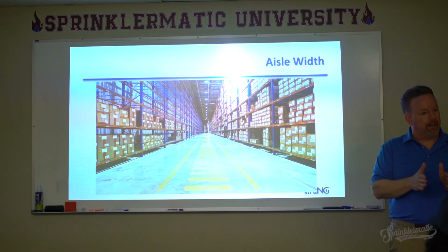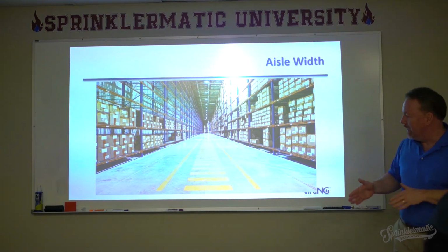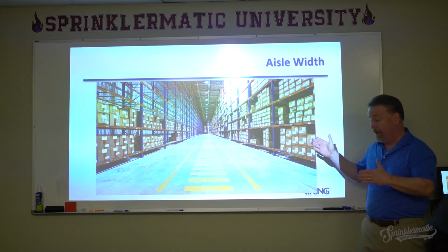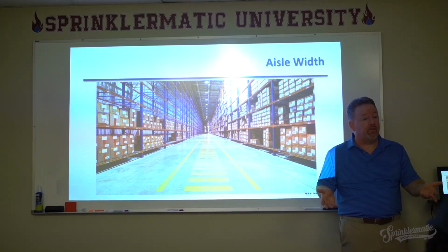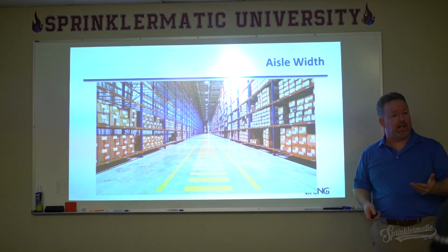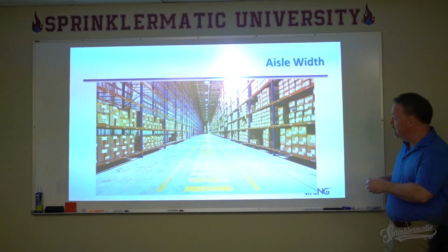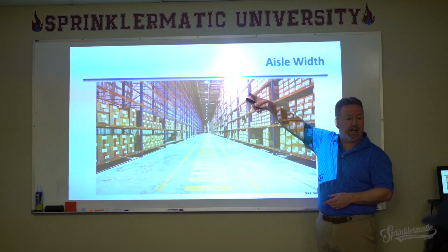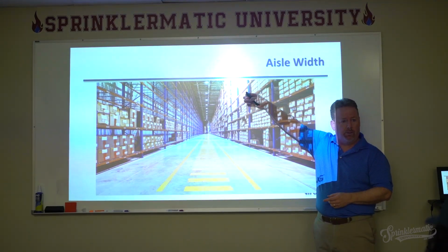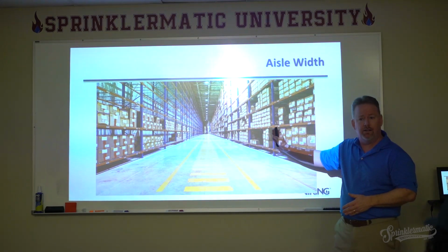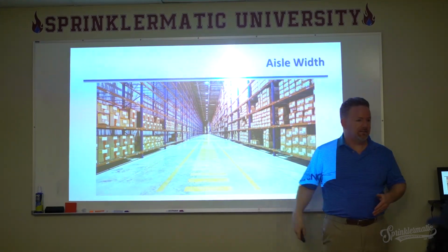Yep, I see wasted space. How do I get that closer together? Stack them on the floor. Right. How do I limit that? Well, I can go 4 feet, but what's a 4-foot aisle going to do? That has an impact on my sprinkler system design. Why? Because if I get a fire going here, and it starts rolling up the outside, burning this, if I have another aisle only 4 feet away, it's going to jump the aisle, all right?